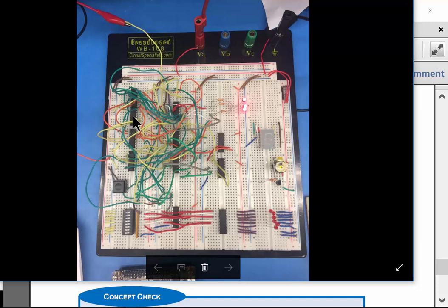So you've got to follow good design, or good implementation, rules. First of all, build 1 circuit at a time. Make sure that you get each term working before you move to the next term. The last thing you want to do is build the entire circuit, turn it on, and it doesn't work because you don't even know where to start debugging. So for each of your logic expressions, go through and make sure that each term is working. Every AND term is working, every OR term is working, every inverter. So build it 1 at a time.